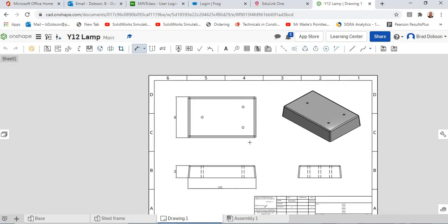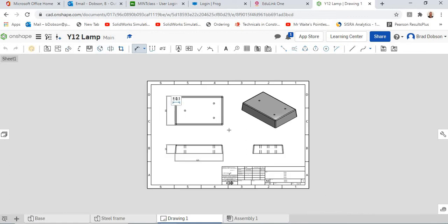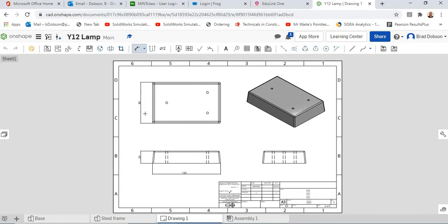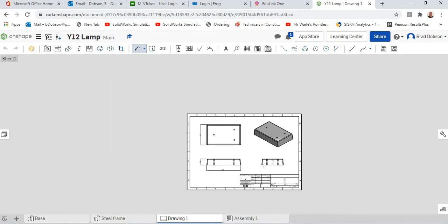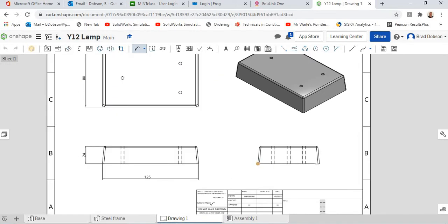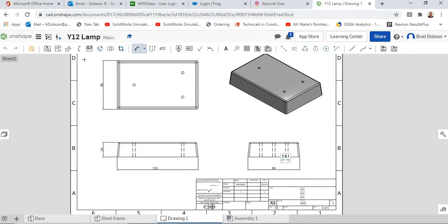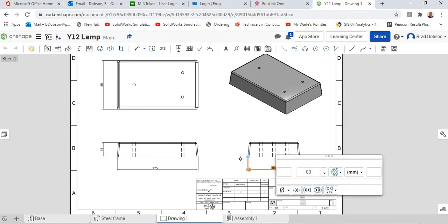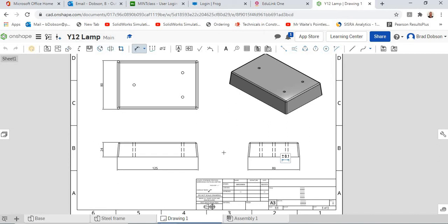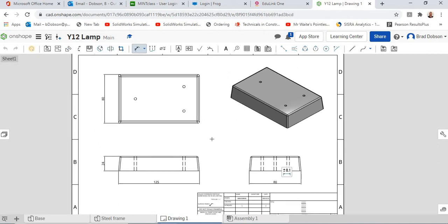One thing to note that people quite often get wrong is double dimensioning. So in theory we already know that width. What quite commonly happens is people will dimension that bottom one. Realistically that's a dimension that's not needed because I can work out that dimension from that view. It's basically the same one, but again, it's just good practice not to double dimension if possible. So we'll put our basic dimensions on there.